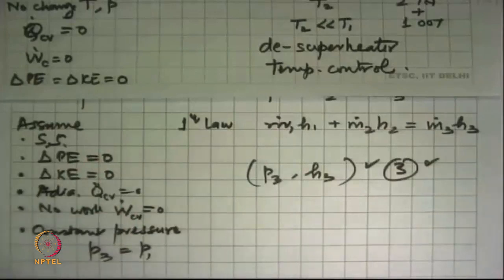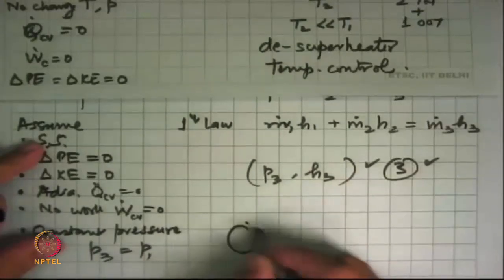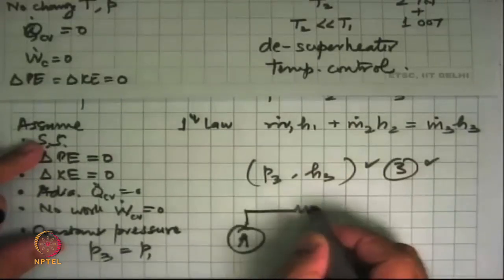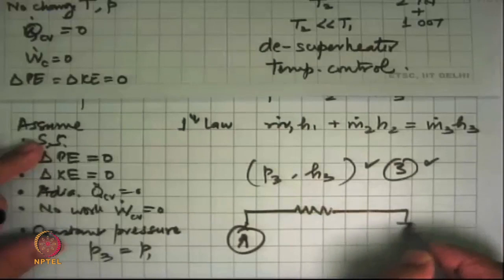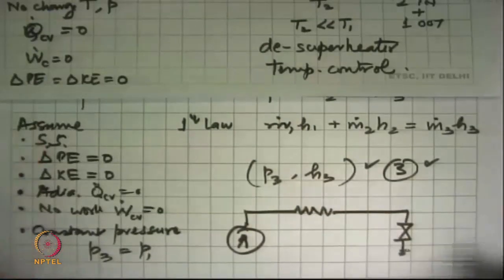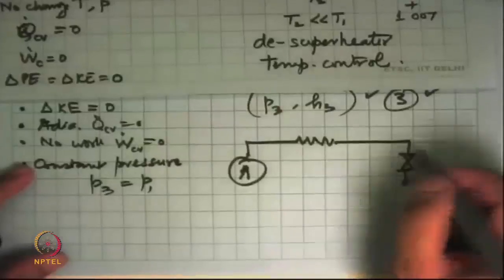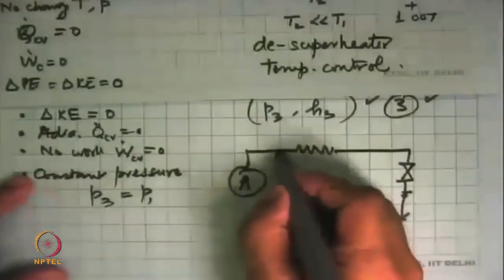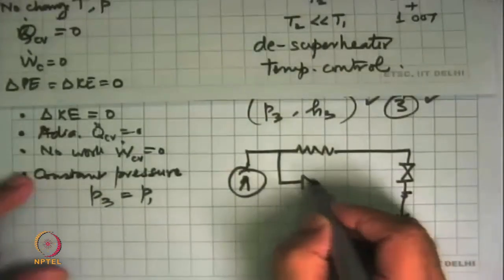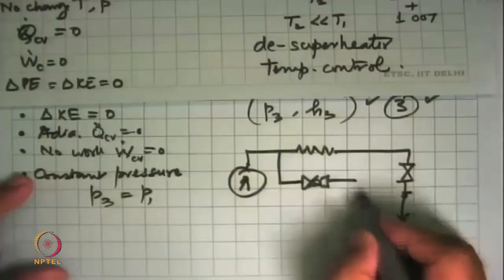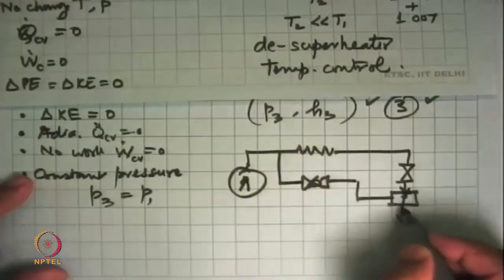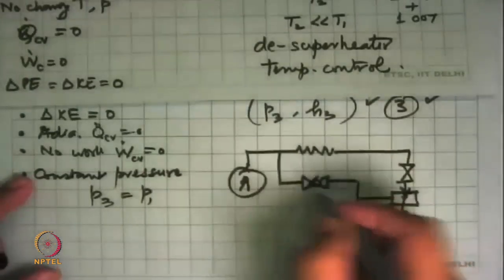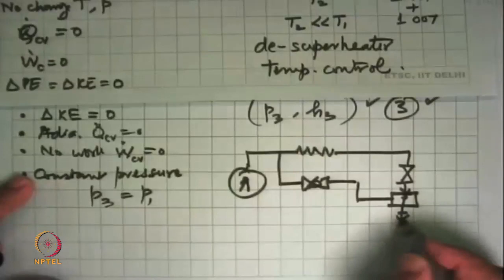A similar thing is also done in refrigeration systems and air conditioning systems, where you want to control the temperature. Say this is the compressor, and after condensing we have expanded it and we want to control this temperature now. There's very little we can do by controlling throttling in this; there's a very small range one can do. The rest we can do is take something from here, put a flow control valve over there and inject small amounts of this into a device at this point which controls the state over here. So you can control this and adjust the temperature at the outlet over here.